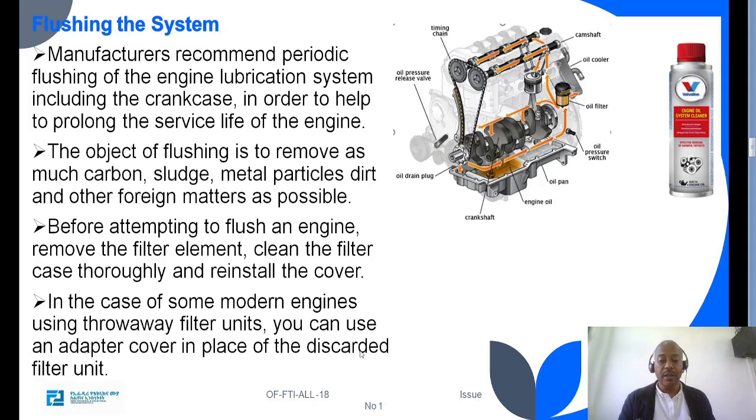Before attempting to flush an engine, remove the filter element, clean the filter case thoroughly, and reinstall the cover. In the case of some modern engines using a throwaway filter unit, you can use an adapter cover in place of the discarded filter unit.